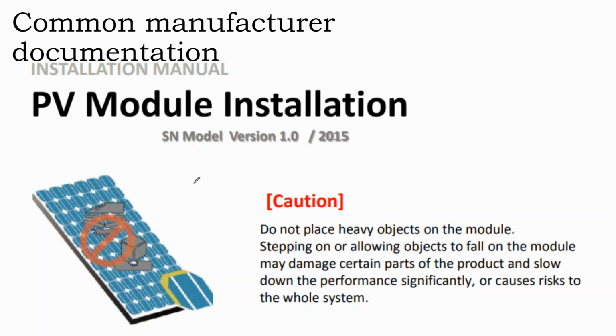The best thing you can do is not put heavy objects on the module surface itself. Don't put your elbows, don't kneel on them, don't lean on them. If you're having to Spider-Man across a solar array, then put that module frame to use, and use the module frame to put your hand or your arm on to get better grip with your installation tools. But what's common is you get the modules on site, and then people want to stack tools and boxes and toolboxes on top of the module pallets before they're installed.